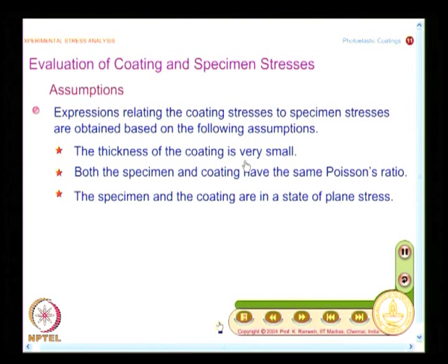and do not think that when I make an assumption we are making a crime, it is not so. I have pointed out that when the Young's modulus of the coating material is much smaller than the base material, even though the thickness appears considerable, it really does not reinforce.